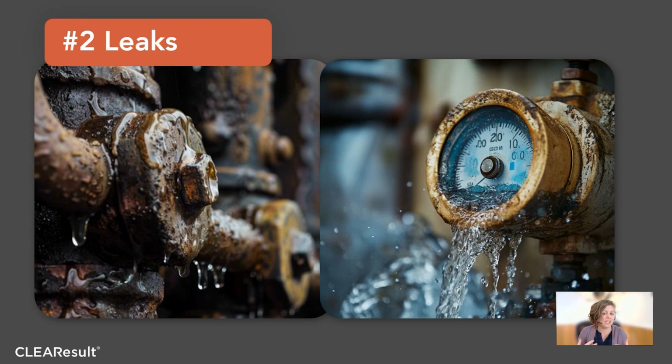Other leaks are heat leaks. For instance, if you look at an infrared picture of your building, you can see where you are losing conditioned air out of perhaps windows and doorways, that's another form of leaks. If you have uninsulated pipes with hot water or steam, that's also another form of leak, a heat leak, which you cannot see, but you can if you use infrared cameras. So take a look, walk through your site, look for anything leaking, not only water or steam, but it's also leaking energy and money.